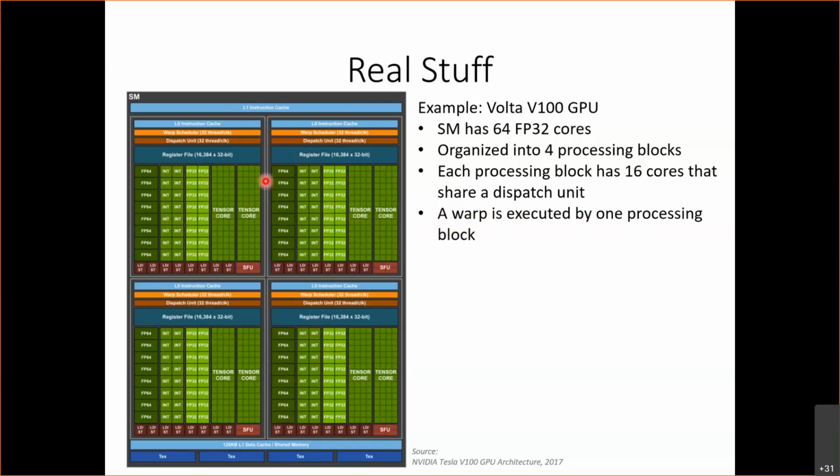But what I mean is that one warp is not going to execute on multiple different processing blocks. The warp is going to be fetched. We're going to fetch one instruction for that warp and execute it for all threads in that warp.